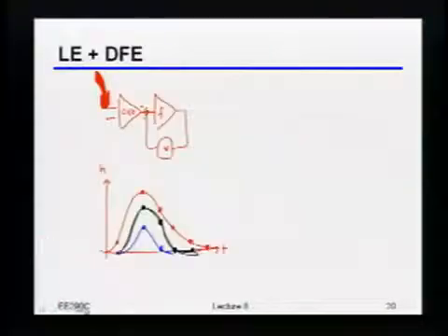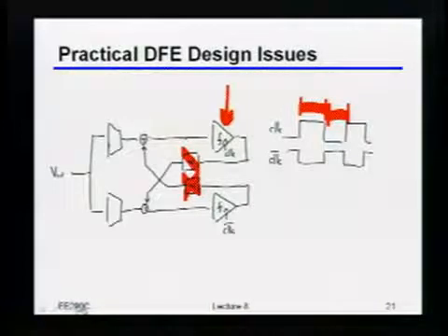So if you end up doing a two-way interleaved design, then you should probably go ahead and do the loop unroll as well. Because if you don't, then it may not really be buying you all that much, unless generating a clock that fast is really expensive. Does that make more sense now? Kind of. It's still not clear that it's that much of a speed benefit, but maybe.